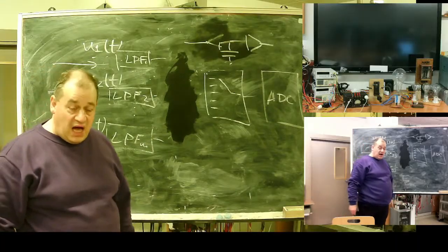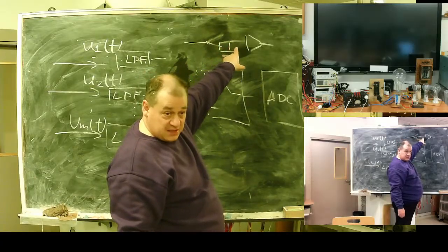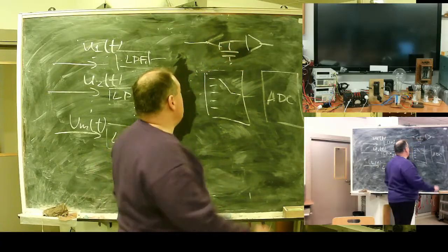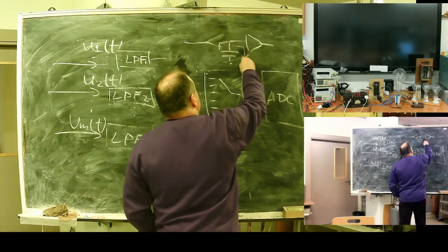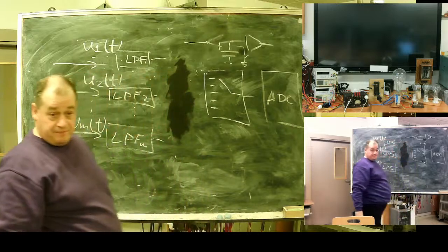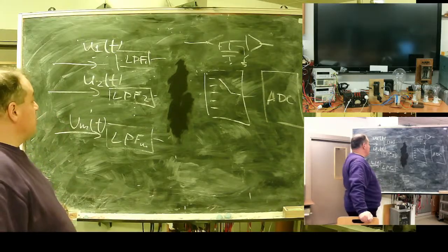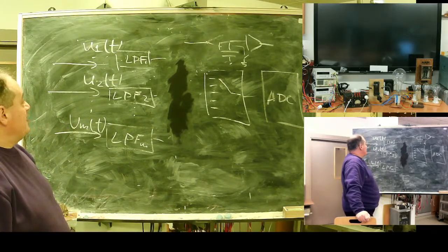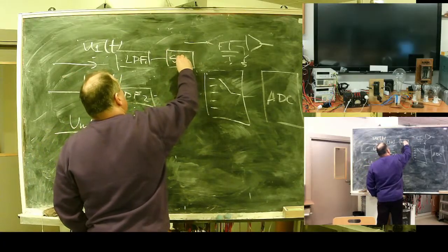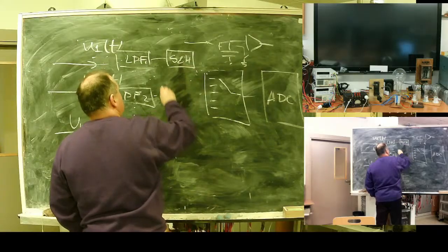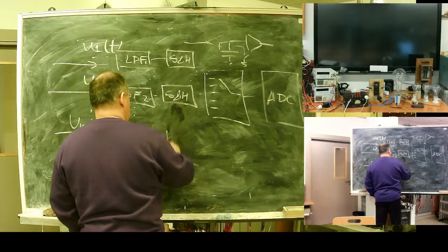When the measurement time arrives, the switch disconnects and the capacitor keeps this voltage. There may also be designs with fast discharge, to prevent back discharging into the voltage source. So, sample and hold.